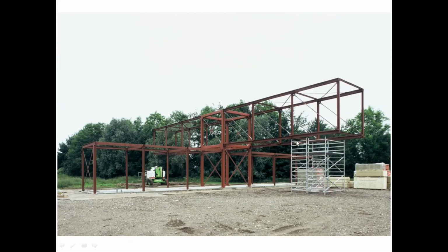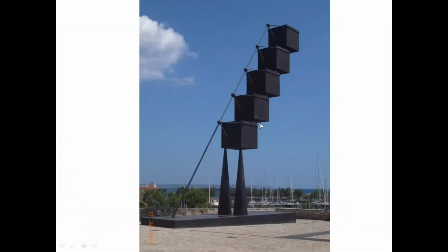It's effectively one beam, isn't it? But it's a deep section now. Here's the triangular, here's the little tensile struts keeping the thing from deforming under any kind of load. And of course it's equally this slightly heavier steel structure at the center here, but the two wings are equally balanced, aren't they? Which is always critical to the cantilever. This is the Calatrava in Palma, Mallorca.